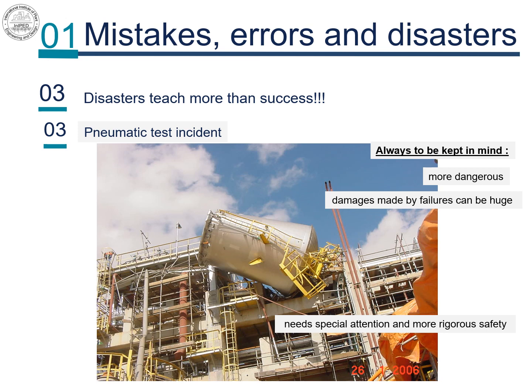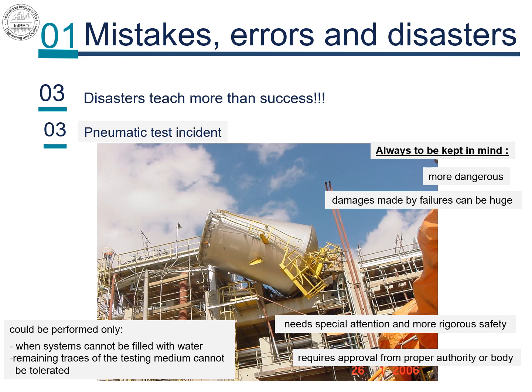Using a pneumatic test instead of hydrostatic requires approval from proper authority or body. Pneumatic tests could be performed only when at least one of the following conditions exists. A. When the systems are designed in such a way that they cannot be filled with water. B. When the systems are such that they are to be used in services where remaining traces of the testing medium cannot be tolerated.